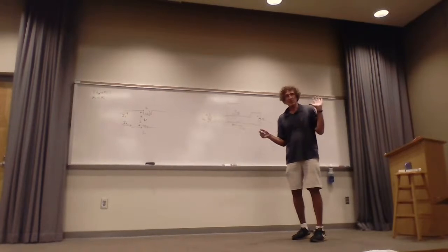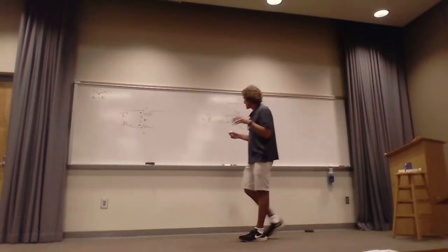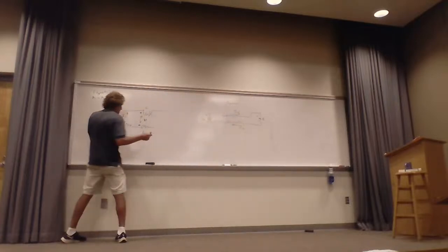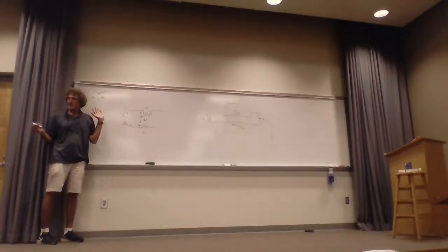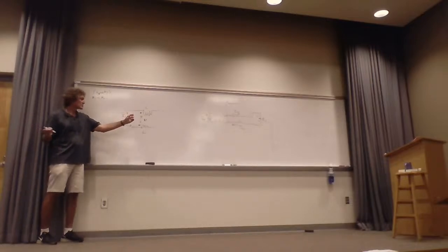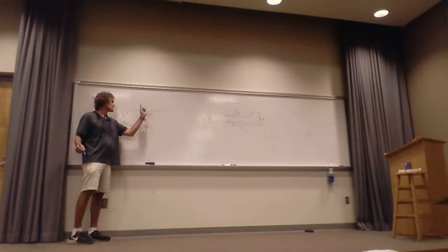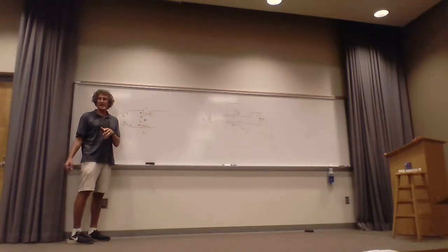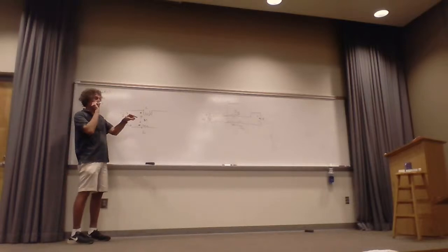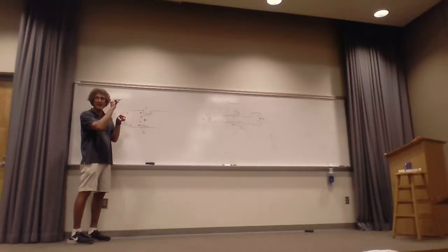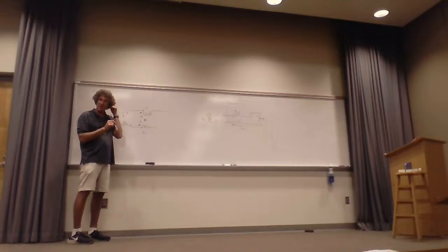How many of you have heard of common mode currents? Common mode is when the current is in the same direction on two connecting wires that connect source to load. Differential is the normal way. We like differential. Got it? So this common mode choke is going to develop a lot of voltage right across here to prevent the actual common mode currents, but it's going to allow the differential mode currents without any impedance. And I'm going to prove this to you. So that's the idea. Anything going sloshing back and forth it likes, and I'm going to show this to you mathematically. Anything that tries to go in the same direction, it blocks.